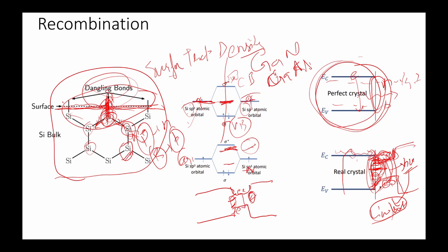So there will be less illumination. Electrons and holes will be recombining, but there is less possibility of going through directly, because there are other possible ways through the traps, which are non-radiative recombination, that we have seen. These non-radiative recombinations kill the performance of the LEDs.